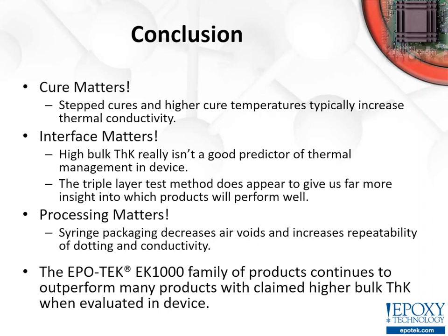We suggest a triple layer laser flash test to give further insight into how the product will actually perform in your device. And processing matters. The syringe packaging process absolutely plays a critical role in terms of the thermal conductivity you can get.